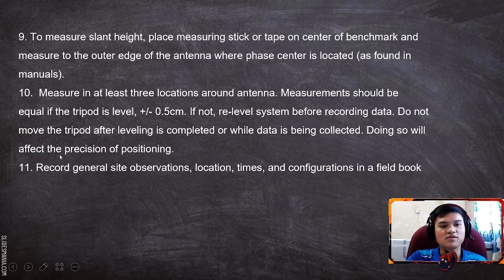Do not move the tripod after leveling is completed or while data is being collected. Doing so will affect the precision of positioning. And finally, record general site observations, location, times, and configuration in a field book.